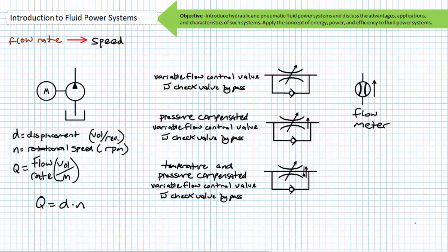A flow meter intended to be mounted vertically, in to out, bottom to top, won't read accurately if it's mounted on its side, upside down, or if the flow is routed through it backwards. A needle slides up and down on a scale, indicating flow rate in the desired unit. Additionally, flow switches and flow sensors also exist to automatically monitor flow rate for electrically controlled fluid power systems.